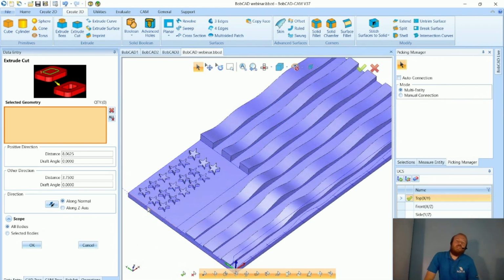Pretty cool stuff. If you wanted the waviness of the bottom stripes as well, you could do essentially an extrude curve. You could extrude cut from the bottom extrude curve that is separate as a solid from the top stripes of an extrude curve, and then do a second cut with the top stripes there.